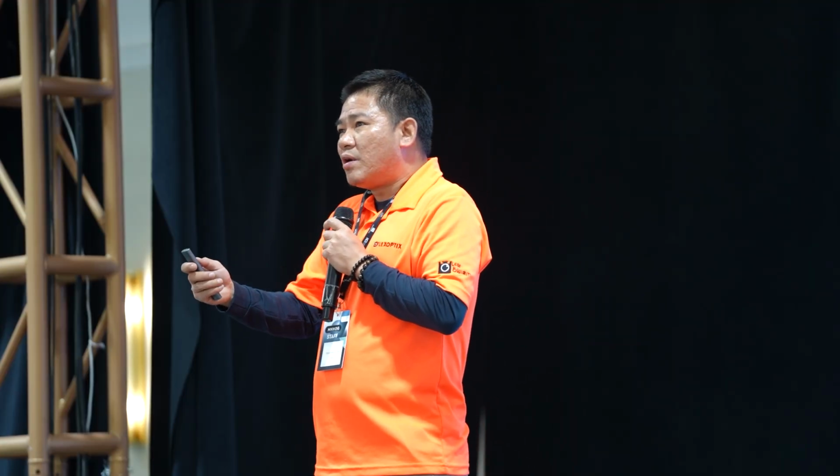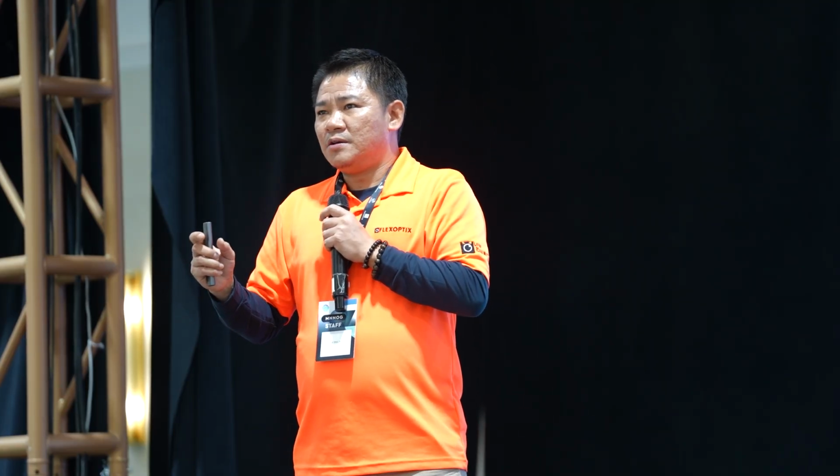When we measure power, we generally measure it in dBm, decibels relative to 1 milliwatt of power, because we need an absolute value, which means we need a reference value. The reference value is 1 milliwatt of power, which means 1 milliwatt is 0 dBm. Minus 10 dBm is 1/10 of 1 milliwatt, 0.1 milliwatt, and so on. That's the first concept for IP folks.